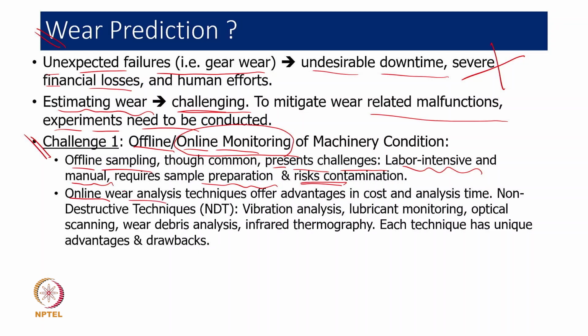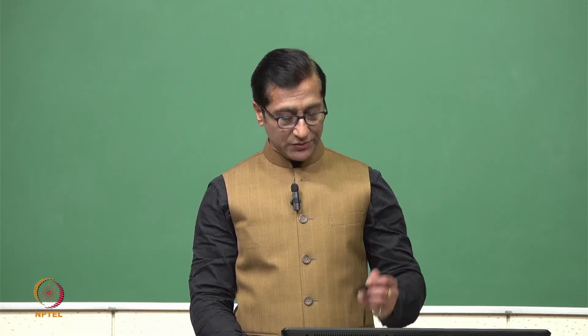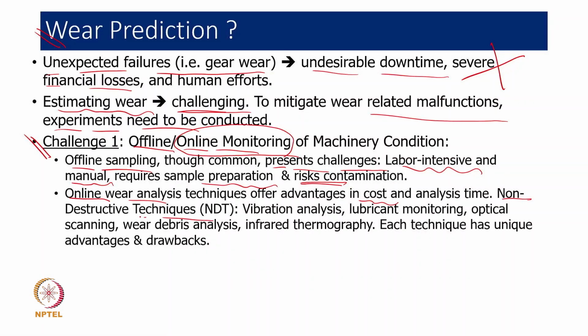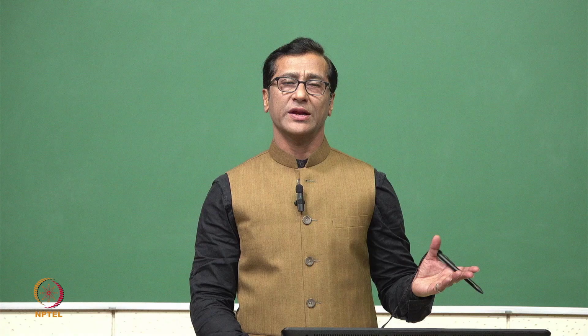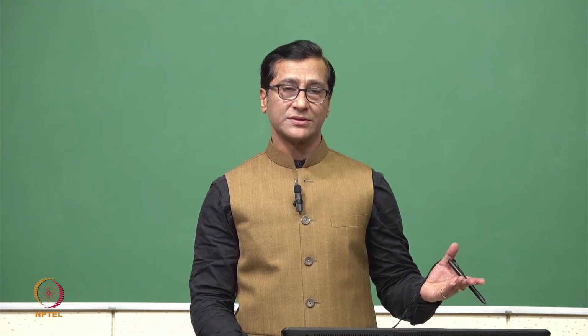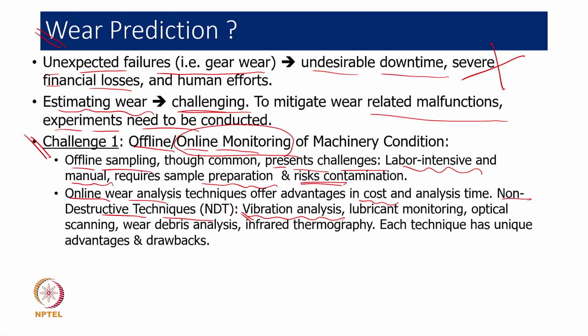Now coming to online wear analysis, do we also have some advantages? As I say, we can get everything in situ, and we can get much faster results in much less time. However, for that purpose, we really require non-destructive techniques. We really require vibration analysis, which is very common. People have been utilizing it for more than 60-70 years. But the question comes, will I be getting everything from vibration analysis? Or even lubricant monitoring, will I be getting all the estimation from lubricant analysis?